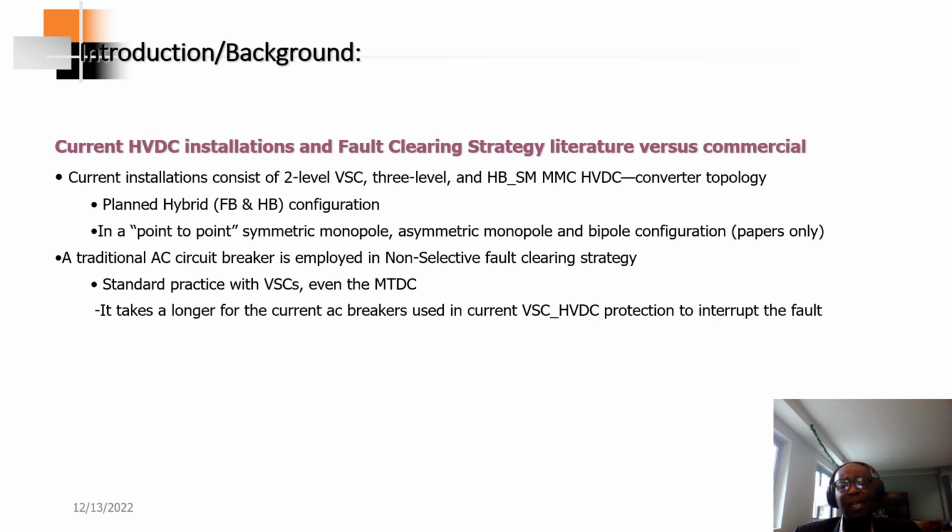As such, it exposes the power electronics components of the converter to this high peak current and can be very destructive. Though there had been several proposals in the literature to mitigate this by strengthening the freewheeling diode with thyristors to prevent it from failing, it basically introduces additional cost.